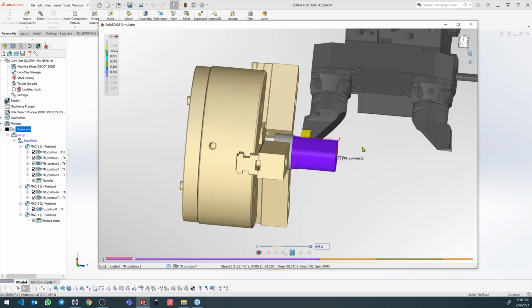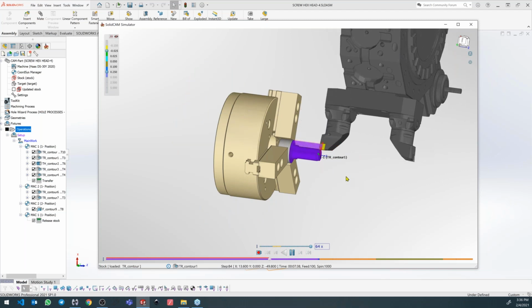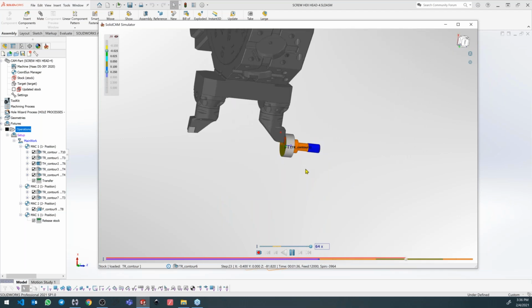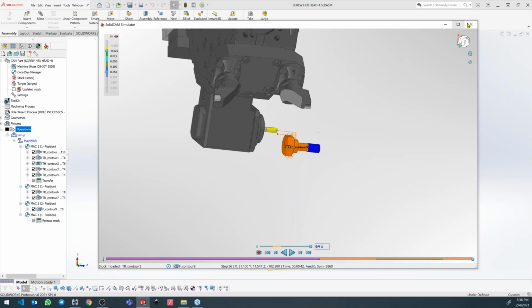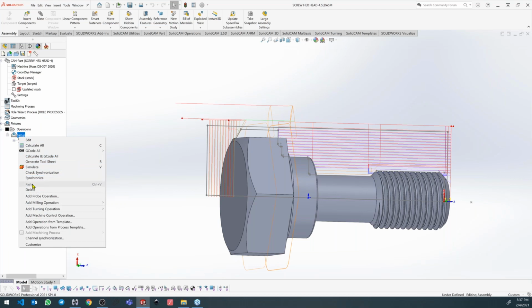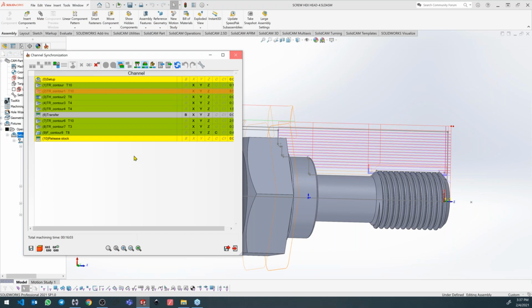Okay, we're starting from the main spindle. Everything is nice. Still don't see my fixture. Okay, important. What I want to do now is to machine this part on both spindles and save the tool change times. On this machine, the tool change time is pretty short, but you still can get a few seconds to find it out.